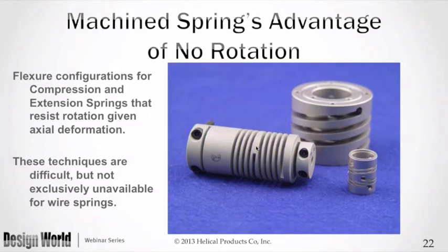There's another spring just to the right of that, the smallest one in the picture, and that is another example of that same idea. It just happens to be a double-started spring. And we're going to talk about multiple starts in just a few minutes. But if we go up to the spring in the background, you'll see that there's two springs there. And what we've done is we have a right-hand wound spring and a left-handed wound spring. And the design is such that the reaction torque is equal and opposite. And so one can then benefit from no rotation in this package. And again, that is a double-started spring. So you get the benefits of the double start and no rotation. That's a pretty sophisticated spring pack right there. That was to be used in instrumentation of one sort or another.